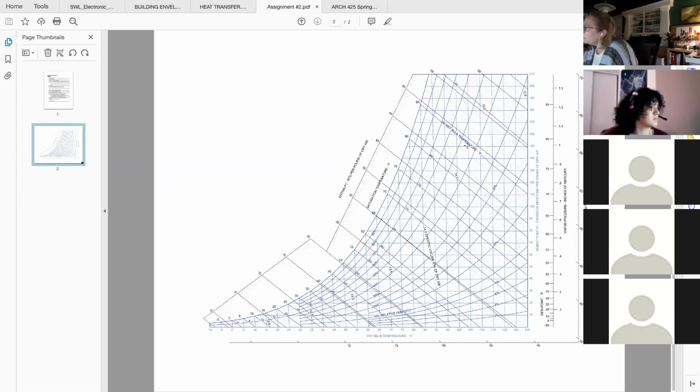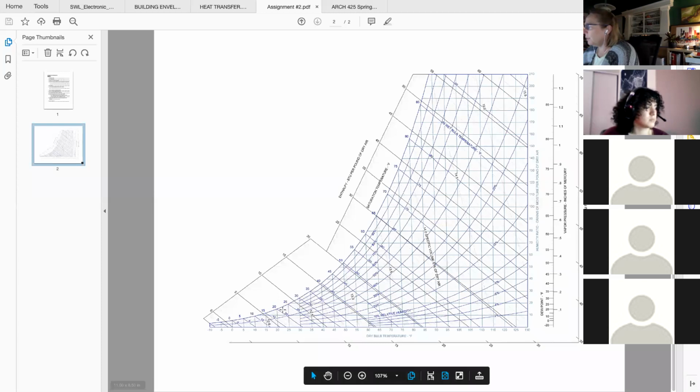So we've got, this is the 85-degree wet bulb temperature, and we've got the 10% relative humidity curve, and this says dry bulb humidity ratio. And let's talk about air temperatures. The higher the air temperature, the more moisture the air is capable of holding. The colder the temperature, the lower the total amount of humidity the air can hold. So at 0 degrees, and this is Fahrenheit, actually let's look at 30 because it's close to 32, which is freezing for us.